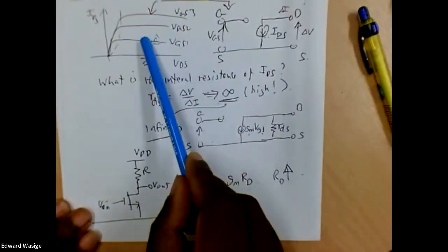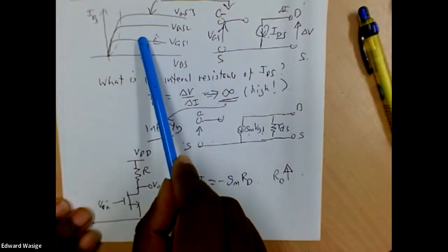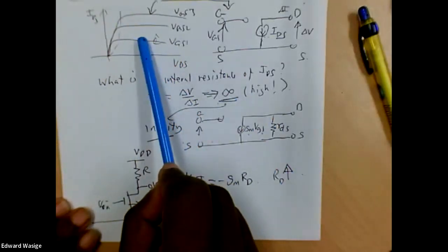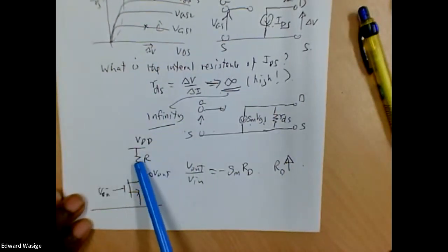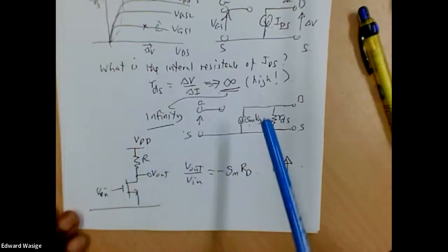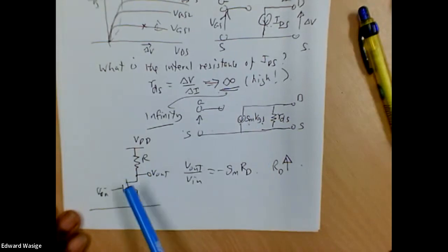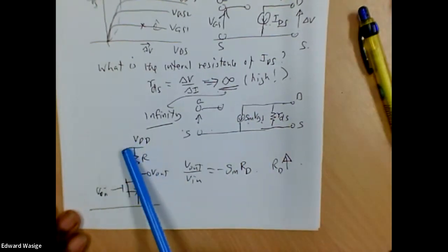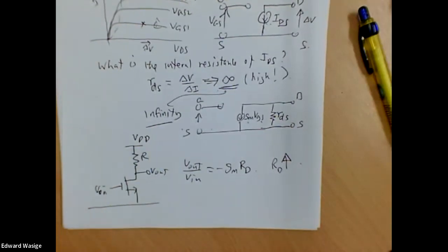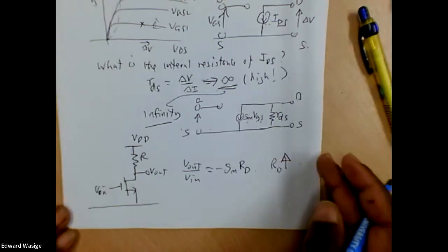If we have a transistor in the active region and put it here, its resistance will be very high, so the gain of our amplifier will also be very high. The reason to use the transistor is that even though its resistance is very high, it still allows a current. The current that goes through this is the same as the current that goes through this transistor here that offers an equivalent high resistance. So if we do that, the circuit would look like this.